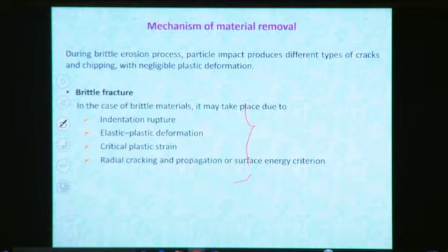But in the case of ductile material, there is also a nominal material removal rate, because when abrasive particles impact the workpiece surface repeatedly in a small area, strain hardening will occur. There is a small plastic deformation in that localized zone, and when many abrasive particles impact the small area, there will be more plastic deformation, and after some time strain hardening in that area.